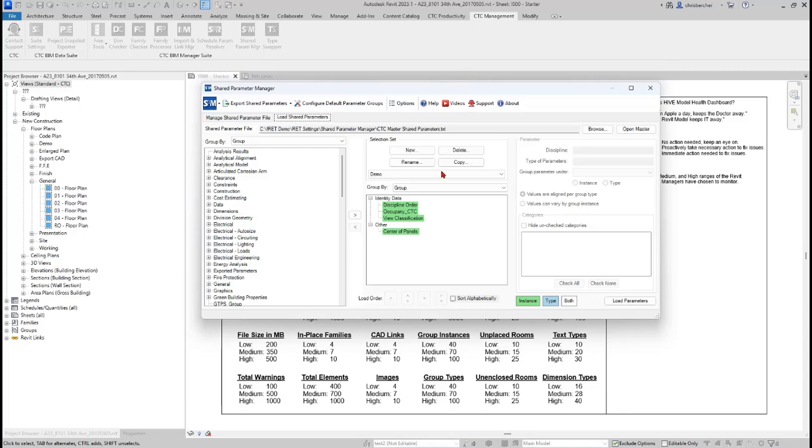So what you can do here is create a parameter set. And maybe it's for healthcare rooms, we'll call it, or anything really. I've got a dozen or a half dozen different ones here for manufacturing properties or door panel parameters or pipe systems or just basic product info with a bunch of manufacturer stuff.